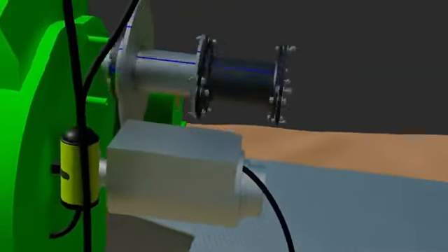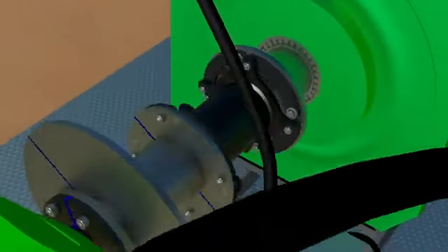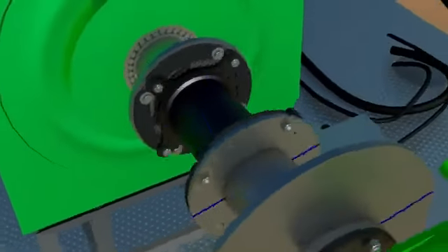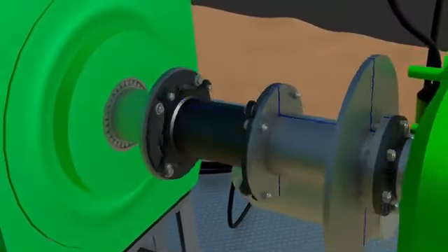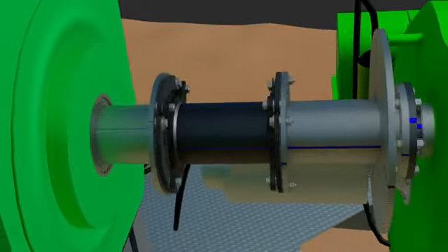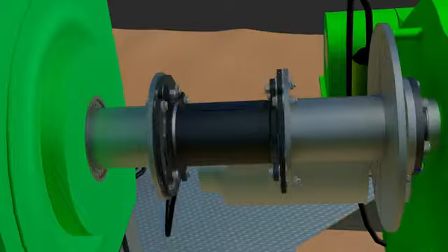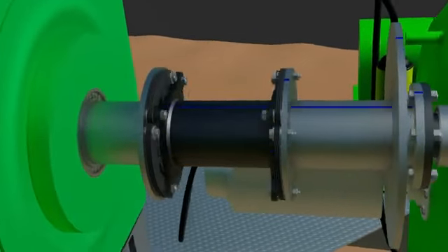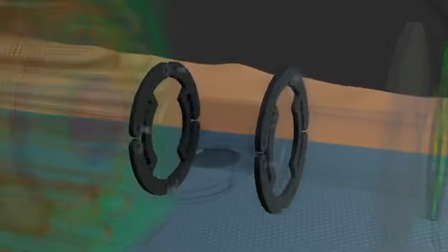A composite disc coupling is positioned between the gearbox output shaft and the generator input shaft. This coupling connects the gearbox to the generator, enabling the transfer of rotational power while accommodating multiple types of misalignment between the shafts. The composite disc packs provide flexibility to absorb misalignments while remaining torsionally stiff to efficiently transmit torque. Critically, this coupling electrically insulates the gearbox from the generator. The non-conductive composite material prevents damaging electrical currents from leaking into the gearbox bearings and gear teeth, which could cause